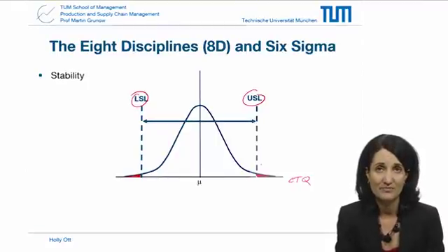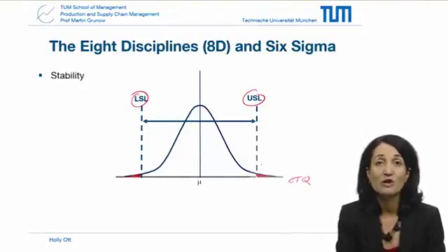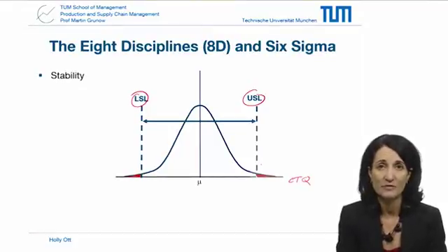Now, often, if we see a special cause in the control chart in our sample statistic, we could have a defect. It could mean that since we've moved out of control, we will also see out of specification on the individual parts for that variable.